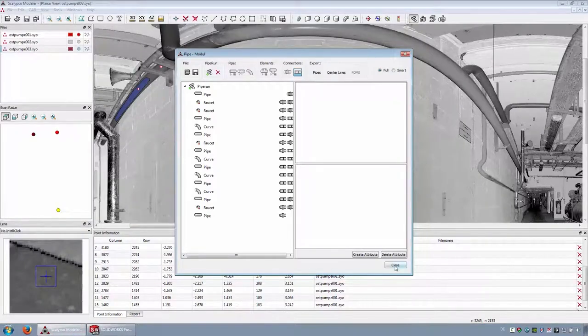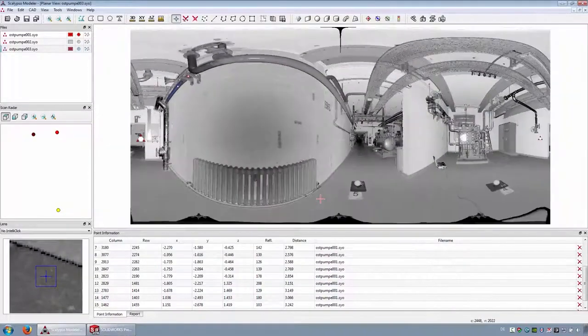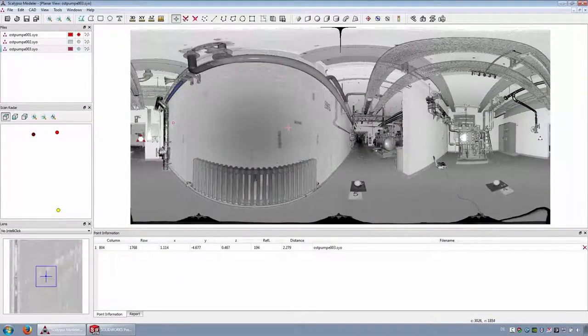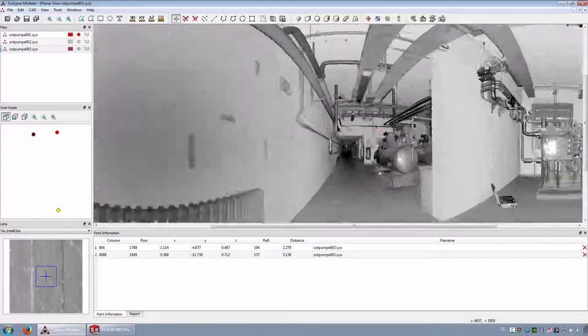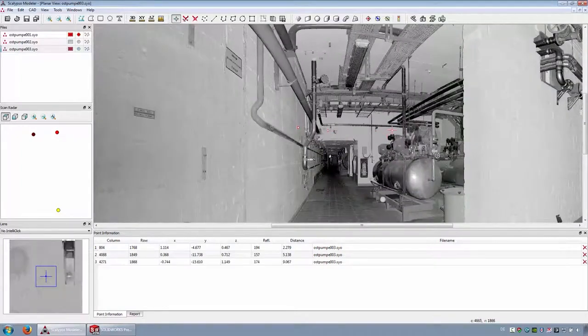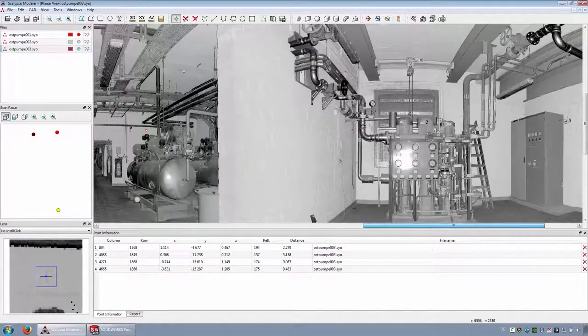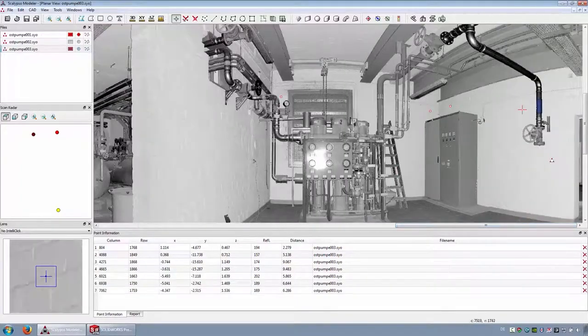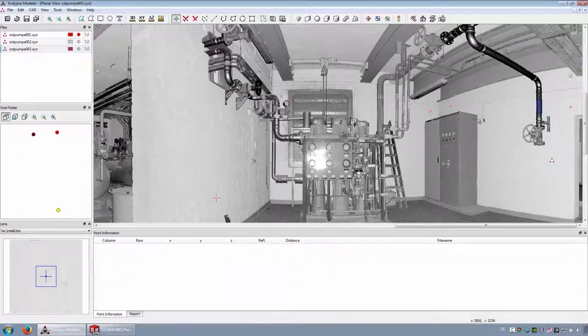Next, the room boundary of the second room should be transferred. For this purpose, again the function export intersection of line segments should be used. 2 points per wall must be sequentially selected. The height of all points must be set to the same value and then exported as intersection.